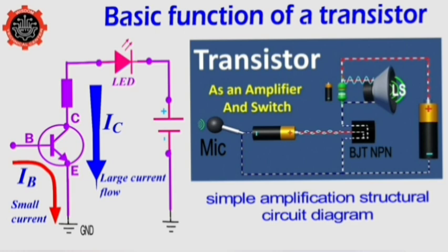So therefore, we can use it as an amplifier. Okay, now let's say an example of amplification could be me speaking into a microphone. The piezoelectric effect of the microphone is going to cause that vibration as a very small voltage. Let's say I get that very small voltage and let it pass through the base of the transistor, where that small voltage is going to control a large amount of current. Now all of a sudden I am amplifying my speech pattern into a microphone through a transistor.